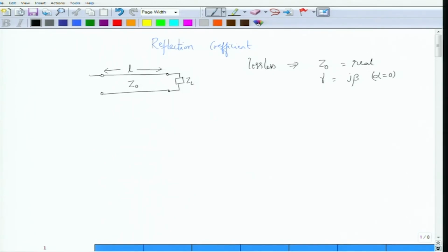To the sending end you might find a generator impedance and a generator voltage. These terms of generator impedance, generator voltage and the fact that this is a generator come from an older terminology of transmission lines where the source was usually called a generator. On the Smith chart as well you will see scales which talk about wavelength towards generator.